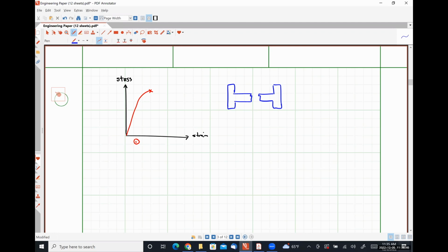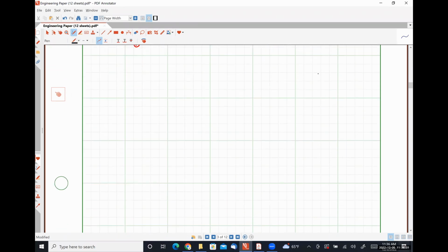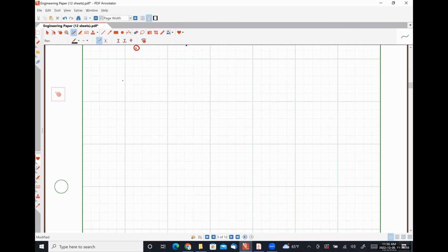All right, so because silicon is an anisotropic material, meaning that specific crystal directions have specific material constants, we are going to have multiple values for our Young's modulus and our Poisson's ratio. So I'm going to give you guys a little table here. We're going to talk about single crystalline silicon in the 100 plane, single crystalline silicon in the 110 plane, and we'll talk more about crystal planes and directions in our next class meeting when we talk about electrical characteristics.